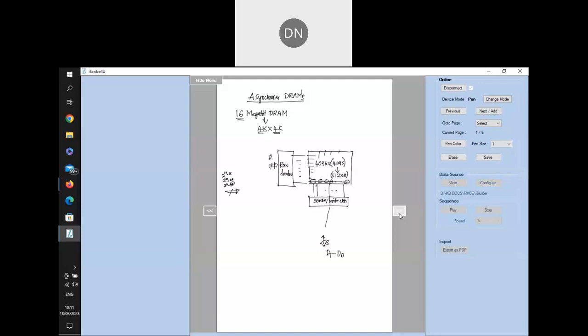After sending the 12 address lines, I'll be selecting one of the rows. Now, in each row you have 512 bytes. I have to select one among the 512. So for that, whatever data we get from the sense and write circuit, I have to give to a column decoder, because I have to select one column. One column is made up of 8 bits. I'm organizing all the 4096 into 512 sets, so each set consists of 8 data bits. To select one among the 512, a column decoder is required.